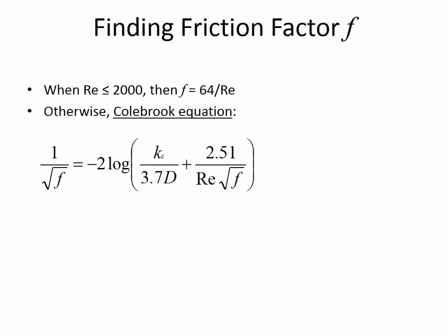So how rough is the pipe? How rough is the pipe depends on a variety of factors. Remember that it depends on the material that you're using. So a glass pipe is going to be much smoother than a cast iron pipe because of the material that's being used.